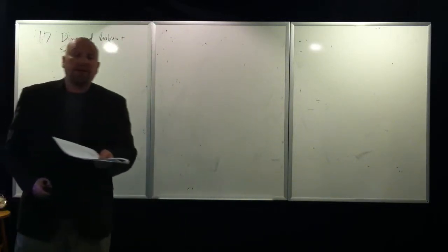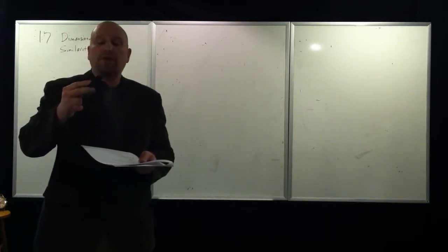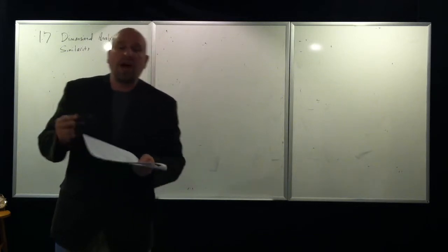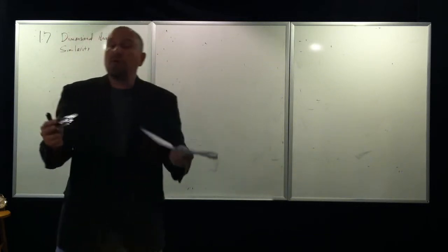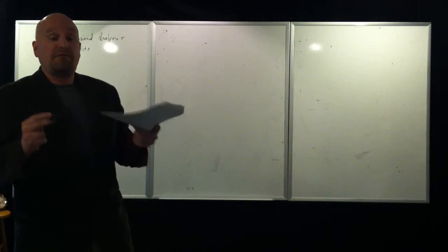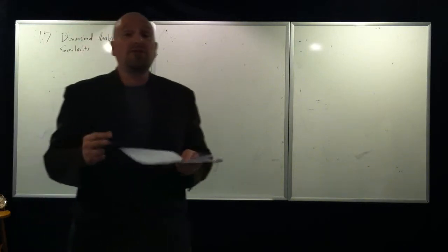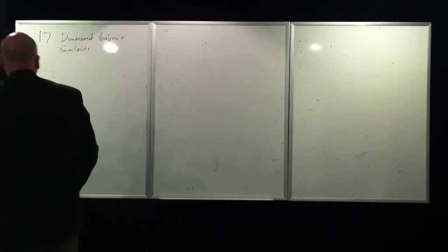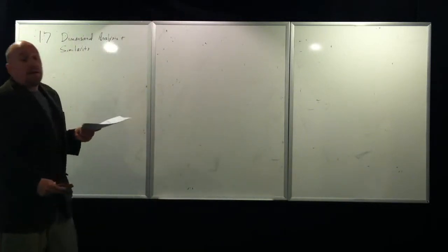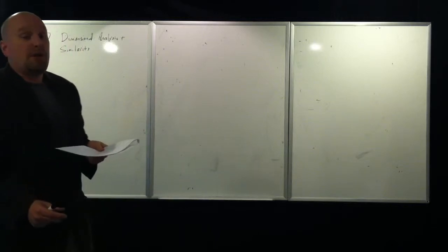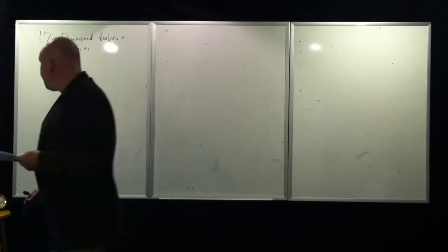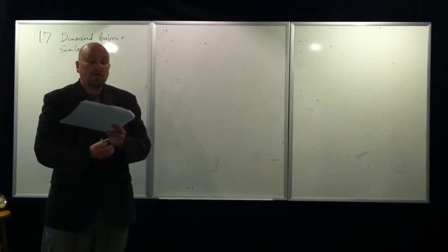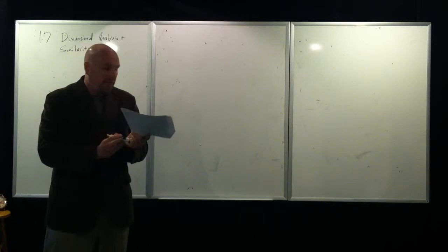The use of dimensional analysis is that it's much easier to work with a model that represents all the important geometry of the prototype, the real physical apparatus that you want to use, an airplane or a submarine, represented in the different non-dimensional coefficients and numbers. So, continuing with where we left off last time, we worked with lift.